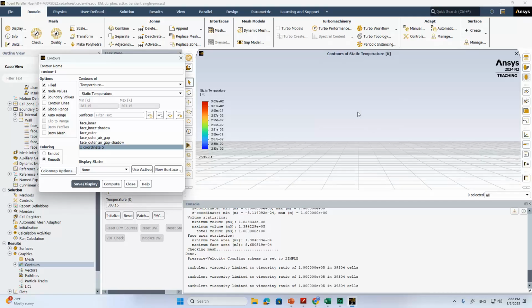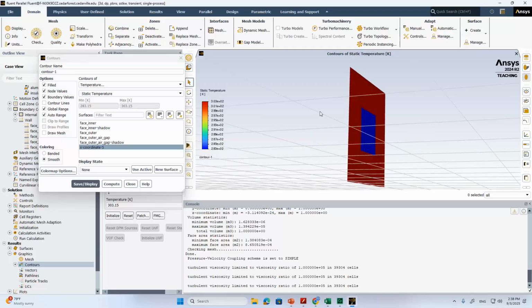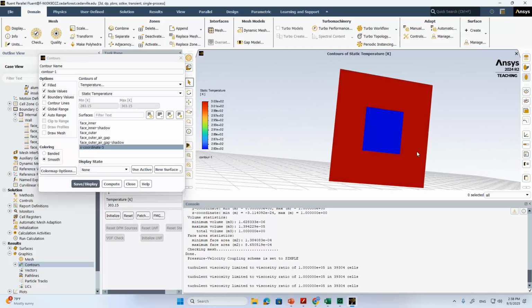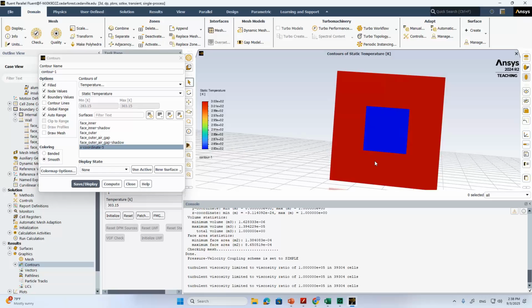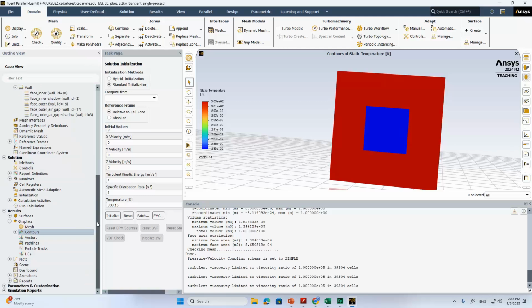In fact, it is displayed, but somehow it is in the wrong orientation, so we didn't see it. So press the middle button and rotate. Okay, now you see it. Now you can see that the temperature, in fact, is correct. Right? We have 30 degrees here, and we have 10 degrees inside the inner container. Okay, now we are ready to do the simulation.